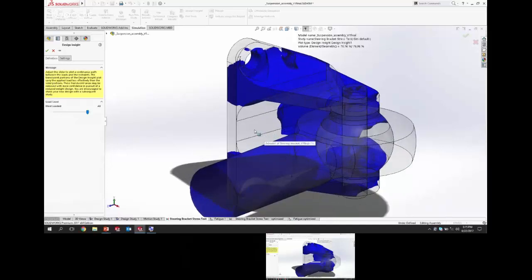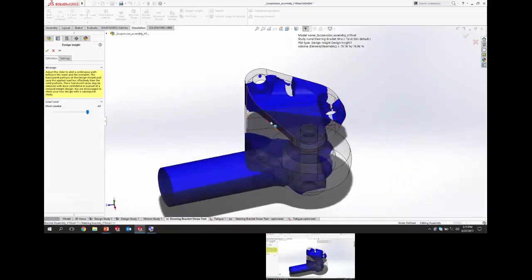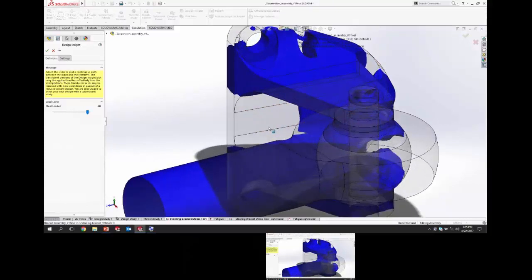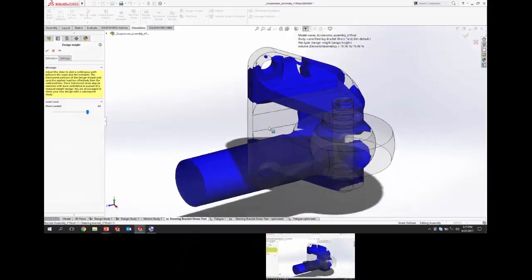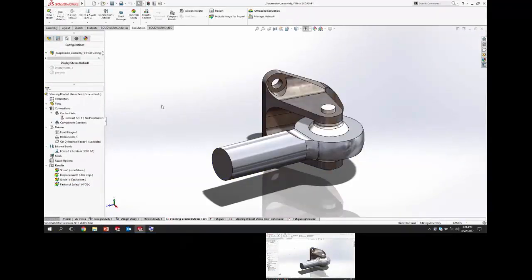Now, it may have some other design criteria, right? That may help us fit it into place, or it may just be simple to manufacture. But that would be a great place to start removing some mass. Now, is that going to stiffen the part, or is it going to make it more flexible? If it is more flexible, is it going to get us too much deflection and too much displacement? So then it feels weak. Is that going to be okay? So if we do that, we do need to still make some design decisions and probably do some more simulation.